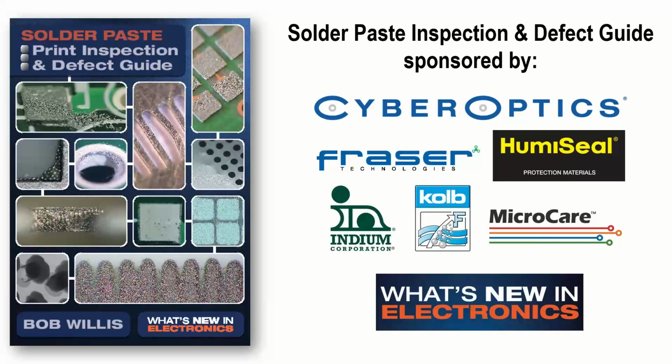So sometimes you might find you're printing beautifully and the roll of paste that's there is actually picking up on the blade. Now, ideally, what you want it to do is not stick to the blade. You want it to sit on the stencil. So again, sometimes those release materials tend to break down, and that might be a reason why you might want to check it.